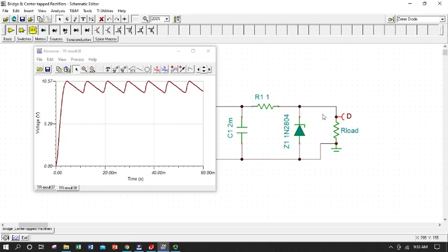So if we were willing to sacrifice some output voltage at our load, or just increase our secondary transformer output to compensate, and we were willing to live with whatever the Zener breakdown voltage is at our load, we would never have that big shift when we switch the current demand of the external circuit, because we're always going to get the Zener breakdown voltage. That's effectively, we've pinned this point at that value.